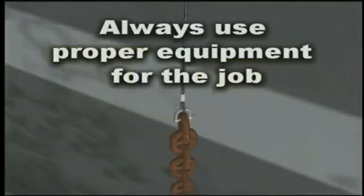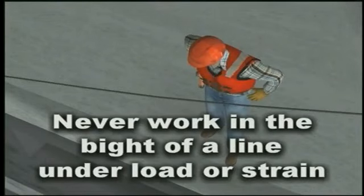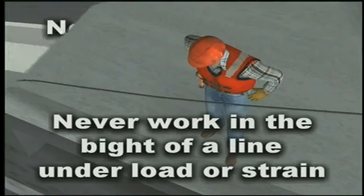A safety line should have been attached to the end of the mooring chain to support it if the hoisting apparatus failed. Always use the proper equipment for the job. The employee entered the bight of the line while the line was under load. Never enter the bight of the line.